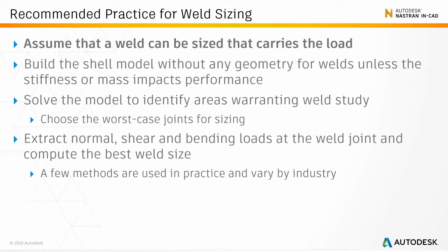Most times though, welded structures are many times the magnitude in size of the weld bead itself, and so leaving it out is not going to make a significant difference in the global response of your product. So once you've identified that the model behaves well, you can start looking at the areas of high stress and investigate the loads going through the welds in those specific areas.